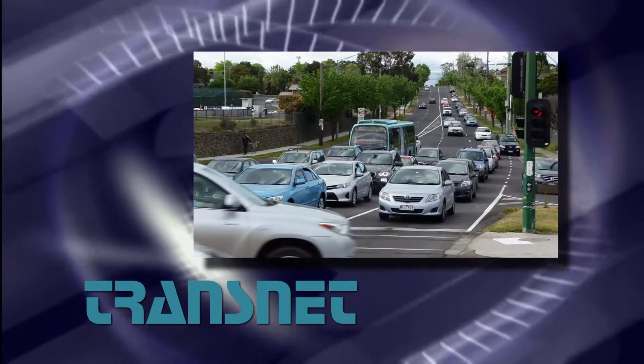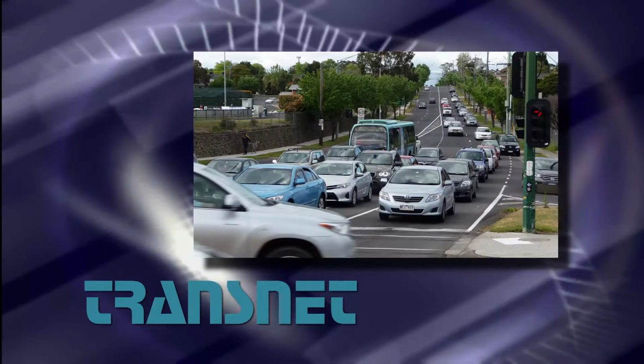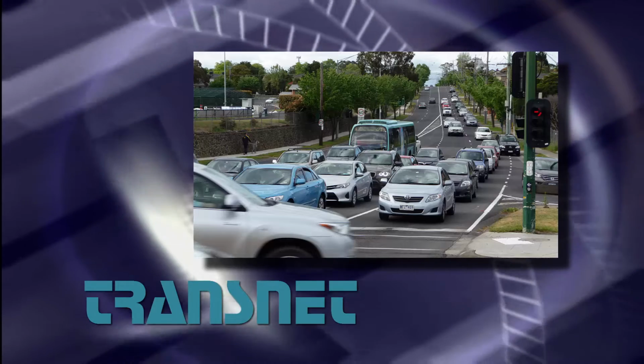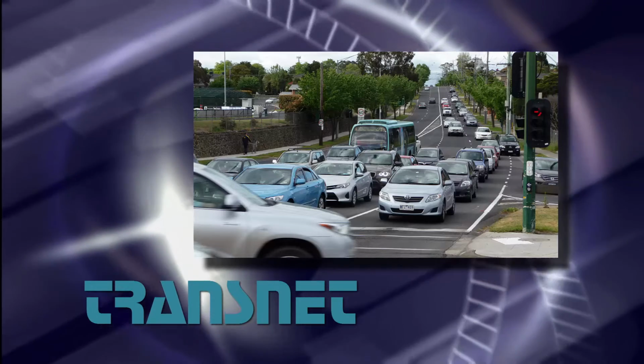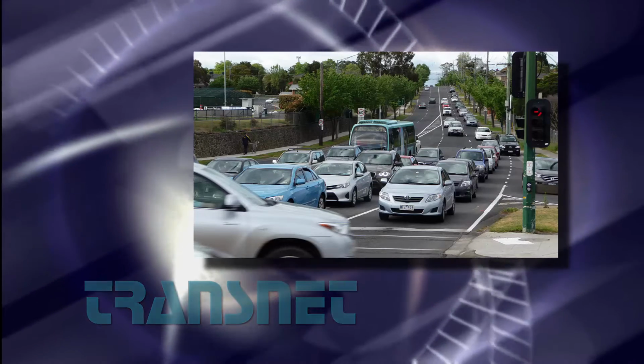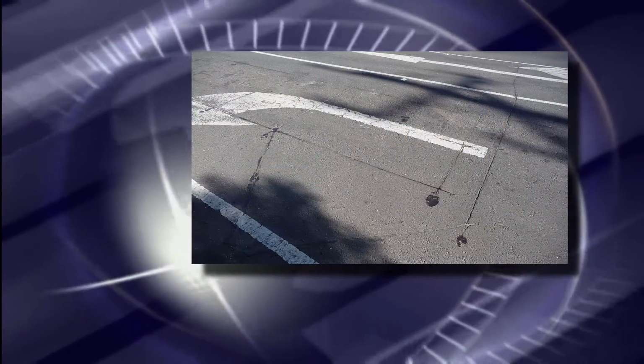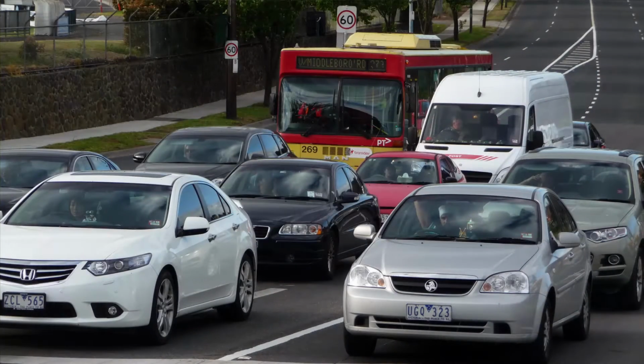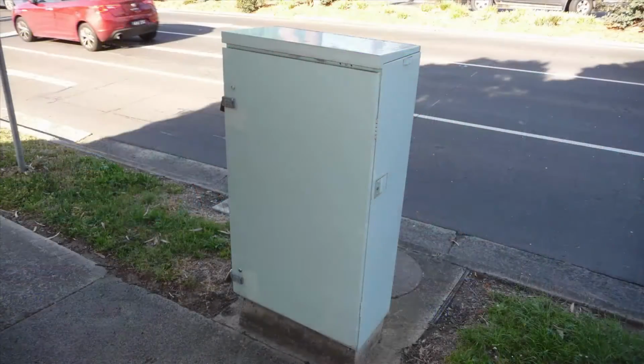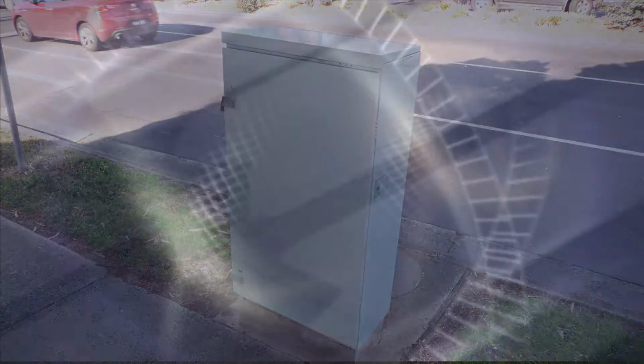Most existing public transport proprietary systems provide a basic and repetitive level of priority to vehicles at signalised intersections, even if priority is not actually required. They typically use detectors that are only actuated by special transponders fitted to public transport vehicles. They also require specialised installation of detector hardware at intersections.